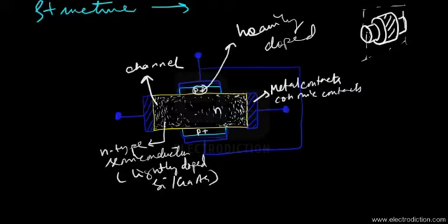In order to curb this problem, what is generally done is this: you can see there are certain dots in the N-type semiconductor bar, which represent the doping profile. At the sides where the semiconductor and the metal contacts are formed, the density of the dots is higher, which represents a high density of doping. I would just like to mention it here: high density doping over there.